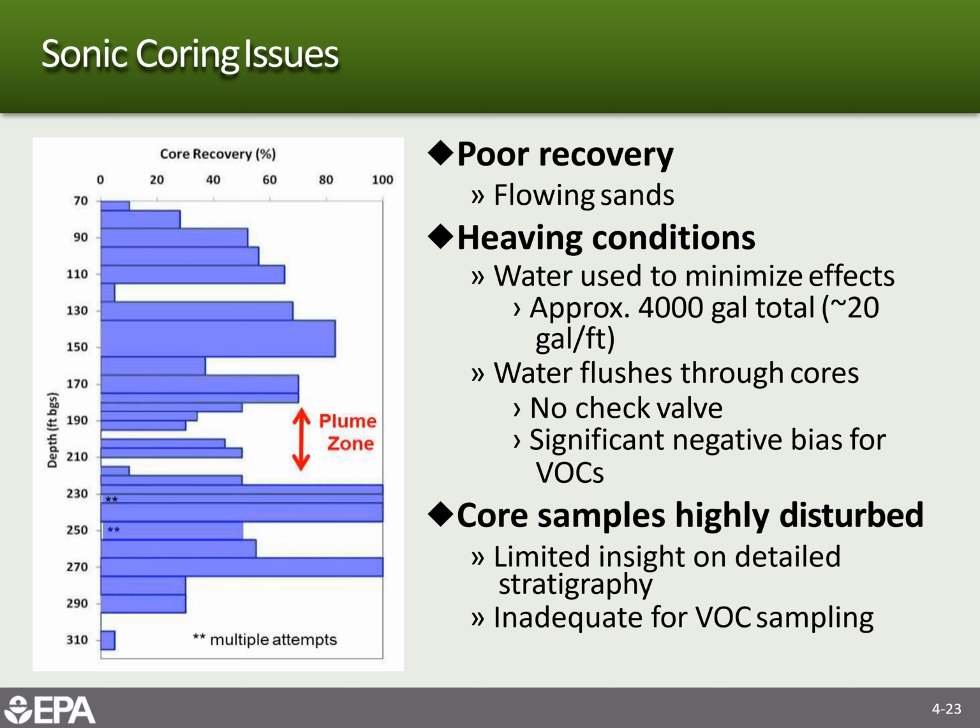It doesn't have to be. I've seen cases where it's come out just fine. Maybe you'll lose a foot or so, but on the big scale of your investigation, having a 90% recovery would be okay, because you'll get very good data off of the samples that you do get. You can get grain size analysis, you can see sedimentary structures, you can see siltier zones that might control the movement of NAPL. But in general, cores are some of the best information you can get to actually see what's in the subsurface.